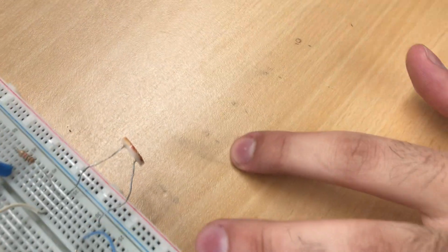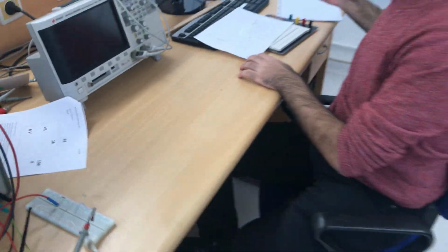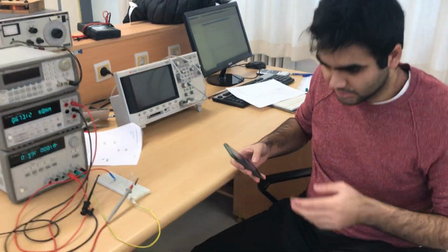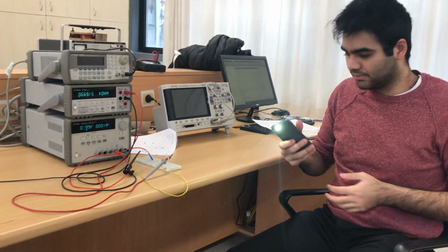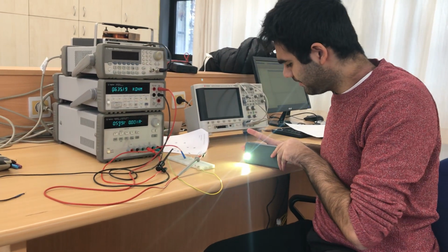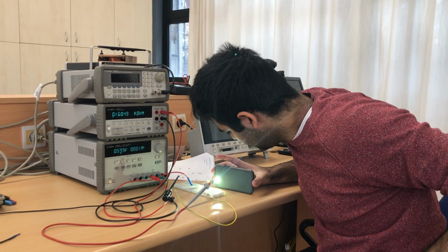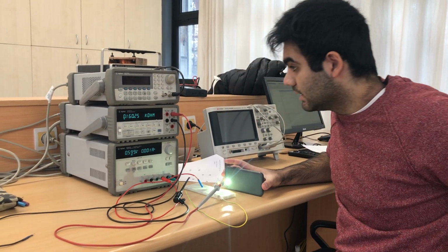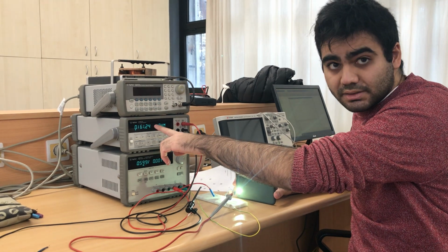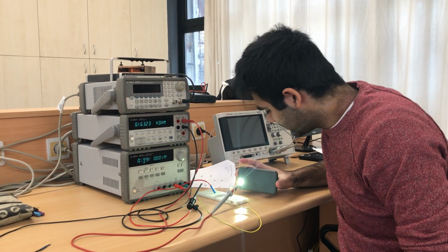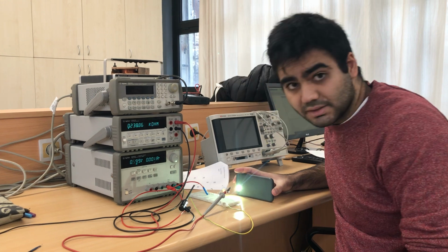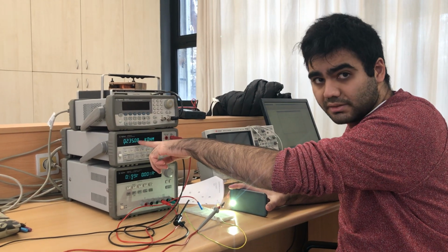I started from 3 centimeters, 5, 7.5, 10, and it goes to 60 centimeters, like this, as you see. I am going to use my flashlight again in the full mode, and I'm going to start with 3 centimeters here, read the resistance value and note it down. Then I will move to 5 centimeters and again read the value.